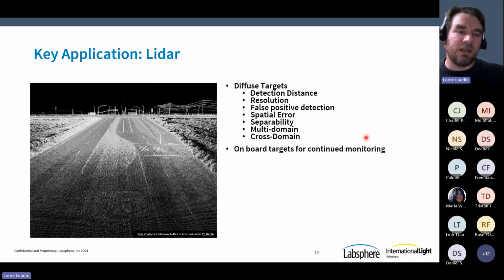And in addition to just being used as a range tool, these targets can be essentially miniaturized, if you will, down to something like 1 inch and actually be used on board with the sensor. So you can get some real time understanding of how everything is performing, right? Or at least how your light source is behaving. So you can add the target into the optical system someplace out of view of the detectors, and monitor what the signal is off of a smaller diffuse reflectance surface during operation.